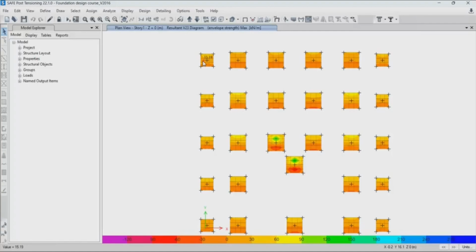Okay, so what you do is a simple division. Let's say you want to use 16 diameter bars, which have an area of 201 millimeter square per bar. The number of bars you're going to use is 1,200 millimeter square divided by 201, which gives us 5.97, which you can round to 6 bars. Okay, so this is for the strip-based method.